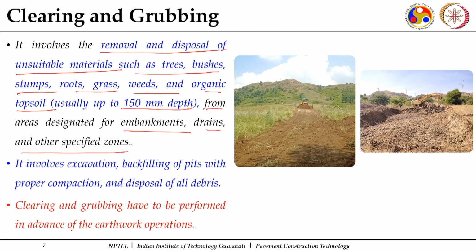So specifically, up to where the edges of your embankments will come up, till that point we'll go for this particular cleaning and grubbing action. So it involves excavation and backfilling of pits with proper compaction. Now this is again important. When these trees are uprooted, there will be pits formed, and they need to be filled back